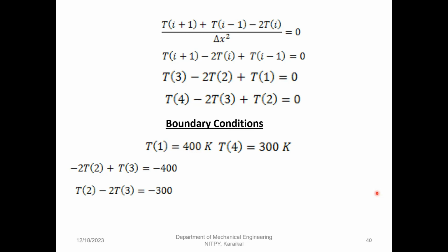Generally, along with mass flow inlet, sometimes they will also be giving the temperature inlet values. So we are giving values for pressure, temperature, velocity, turbulent kinetic energy, epsilon, whatever models you are going to use. We will be giving all those values at all the boundaries. Without that, the system will not be able to solve it. If you don't know the values at the boundaries, again, we will not be able to solve the system. So you must know the values at the boundaries, or you must extend the boundaries till the value is known locally.